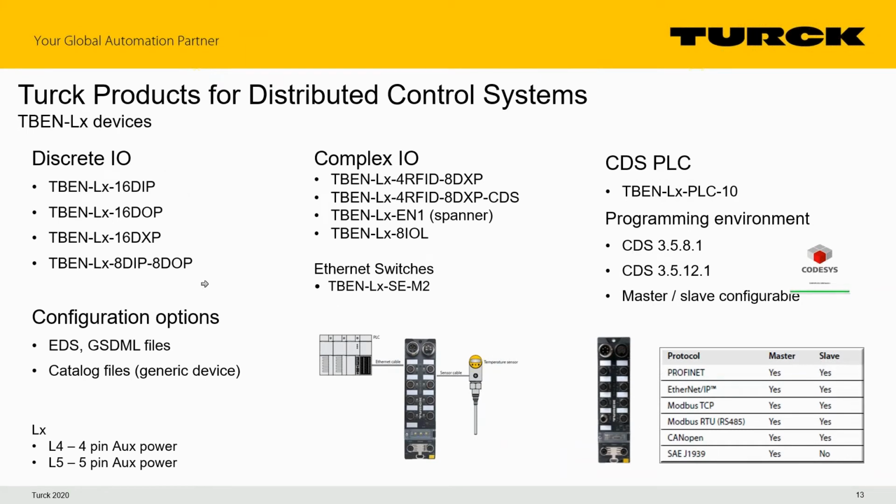So what can we do with these blocks as far as I/O connections? We can do 16 inputs, 16 outputs, or 16 configurable, and there's no real configuration to it. You wire it as an input, read the input table, it's an input. Wire it as an output, write to the output table, it's an output. And we have a half in, half out block.